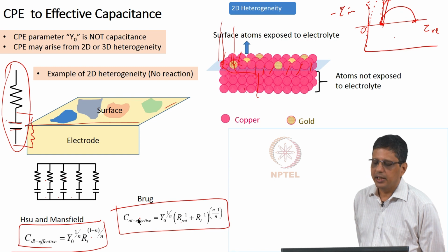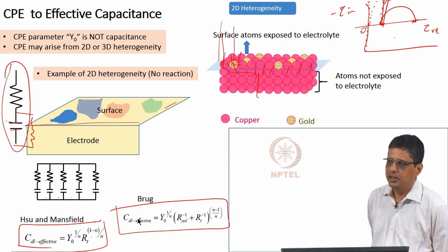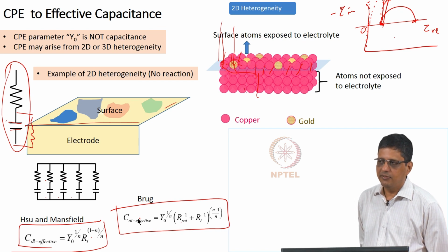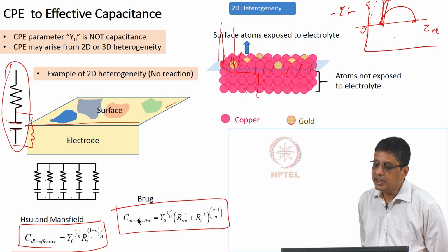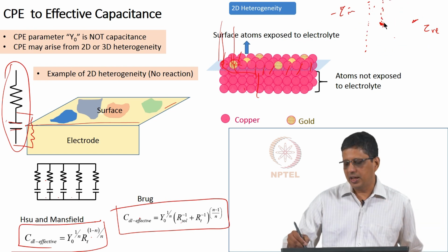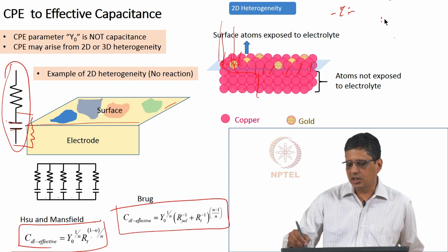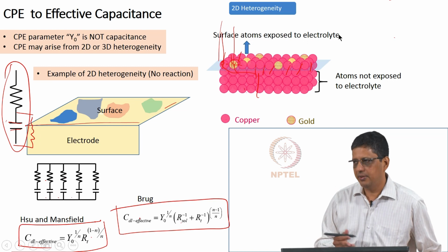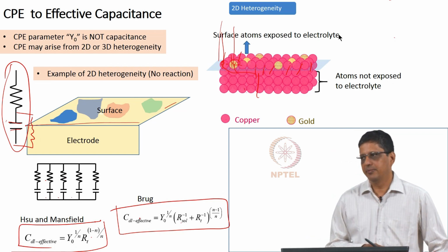Maybe the conductivity is more or less, I mean at this level the conductivity difference is not really significant. Meaning we are measuring few ohms, few milliohms, etc. Yes, there is a difference in conductivity, but that is not causing it. When we have copper wire, aluminum wires, little longer wire, shorter wire, by and large you will not see much difference in the impedance measurement.